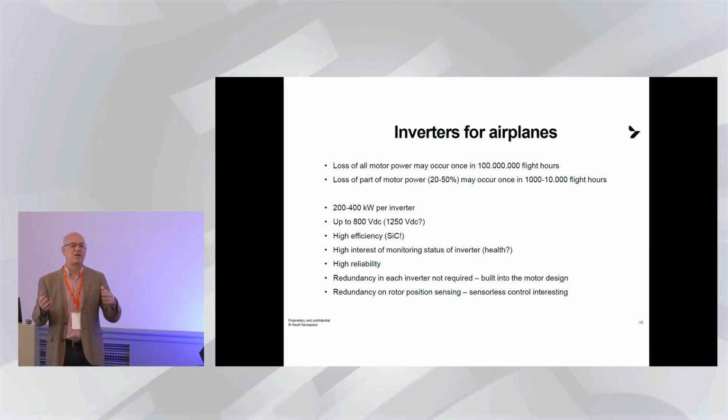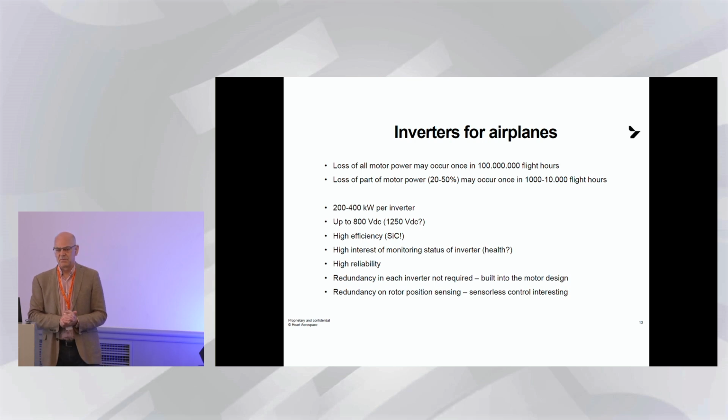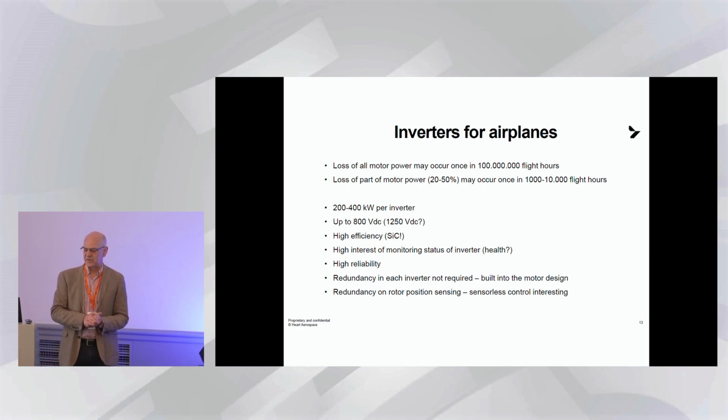Even if the fault is kind of minor, if we lose just one inverter, it still takes time to change. So very, very good if we have good status monitoring. Reliability is still high, yes, but similar to the automotive industry. Redundancy in each inverter is not required.